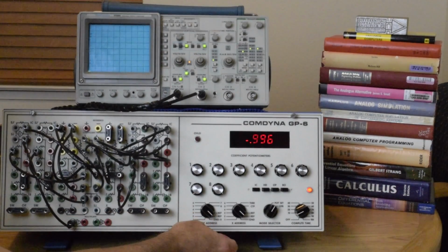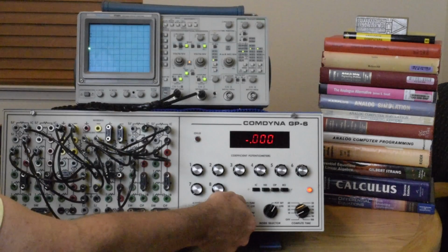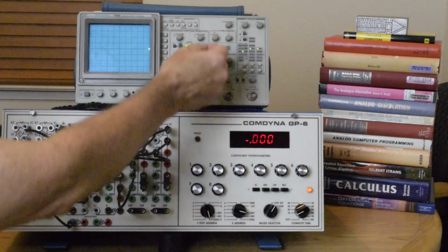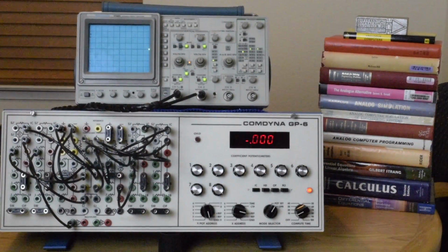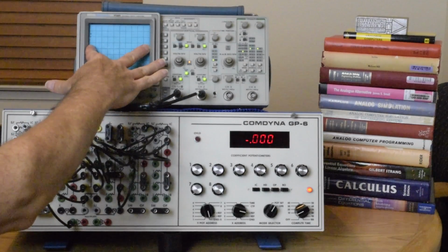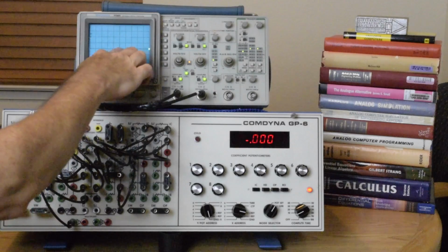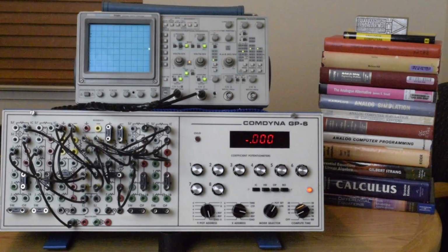And then, sorry, I went to the Y switch. Same thing on the other side. So you might have to go back and forth and adjust those in, but once you have the maximum excursion and the ground set calibrated, you can actually read off the individual time parameters off of the x-axis of the scope.